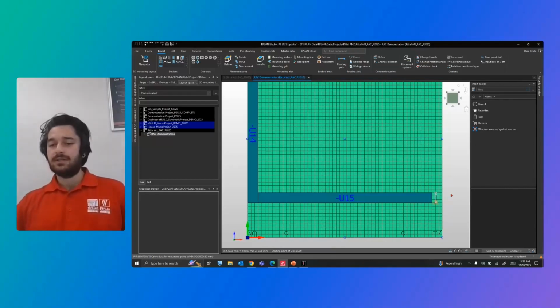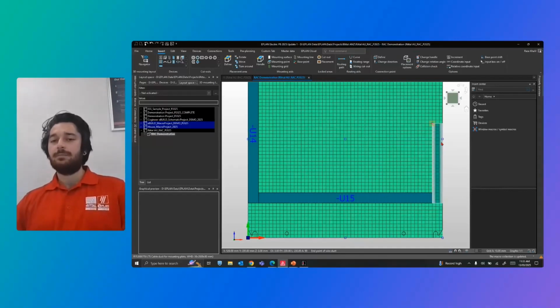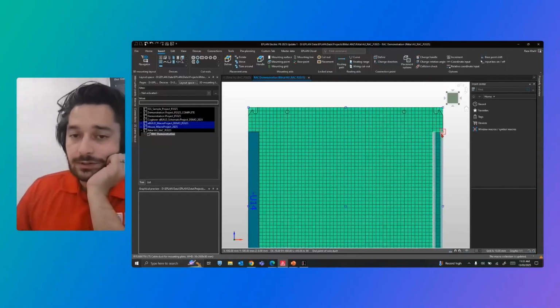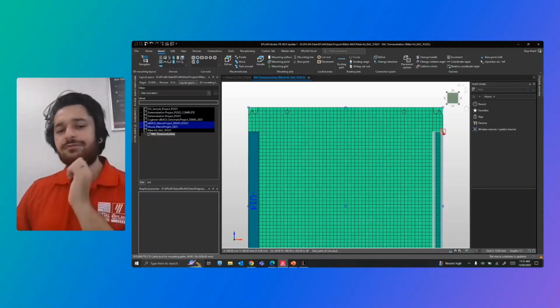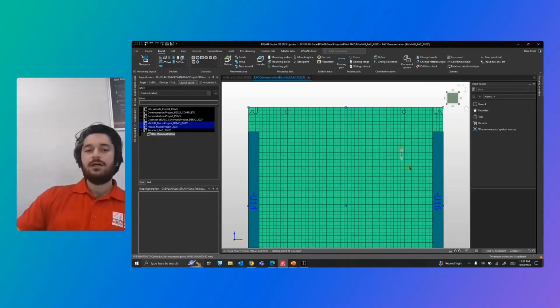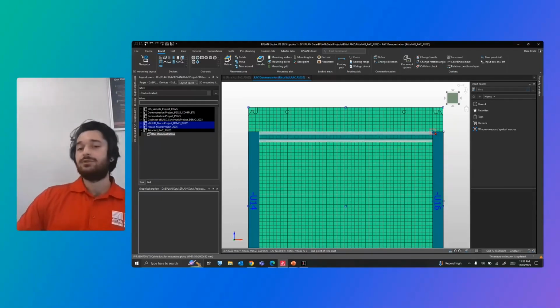I can start from this side now. Press A and bring it up until, in fact, I can even snap onto this point here. So how much was it? 400 length. So we'll just type in 400. Perfect. And last but not least, simply end to end.